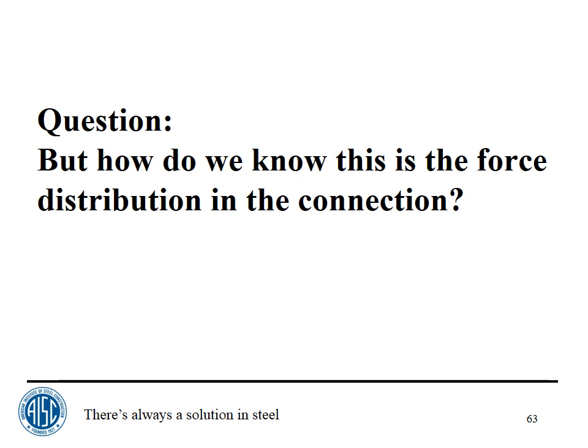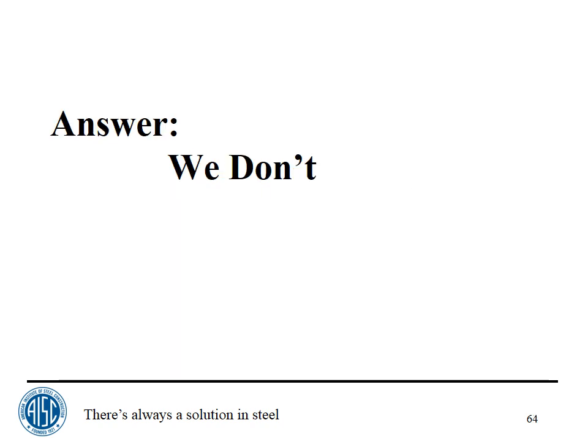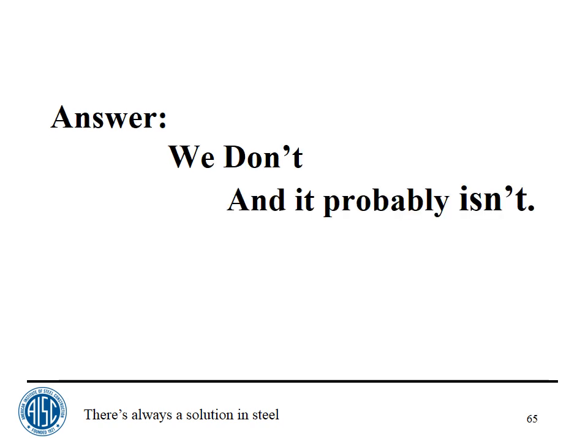Okay, coming back to that force distribution that I showed you from the uniform force method, how do we know this is the force distribution in the connection? And the answer is we don't. We don't really know what the force distribution is in the connection. And it probably isn't.